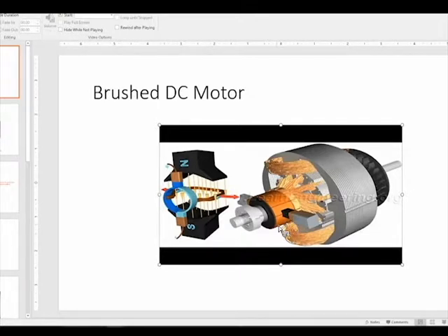Okay, so to note, they're not showing the electromagnet on the outside of this. They're just showing the salient poles. Remember the definition from Monday? This pole here from the stator would either be made of a permanent magnet or it would be made of an electromagnet, which is a coil running around this with a current through it, and then the flux through the stator is directed from north to south in here. So it's not showing the coil, it's just showing the direction of flux.